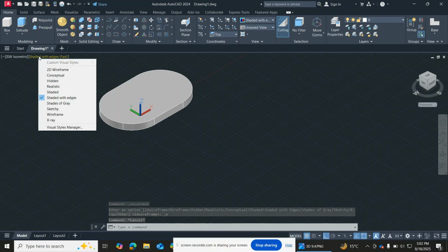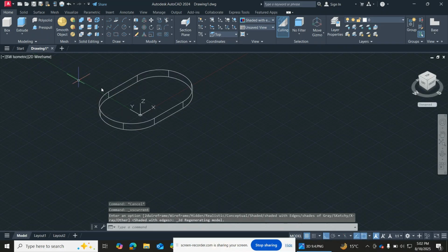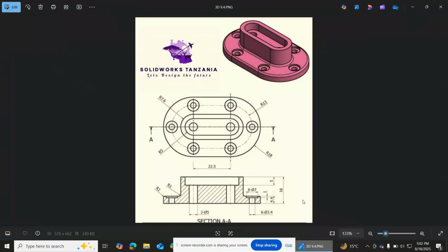Yeah, so let's go back to 2D wireframe to put other features. 2D wireframe, so what features? So I have to draw this guide slot, right? The guide slot has a radius of 13, circles with radius of 13, and then the center lines. Let me do that. And these bigger holes that go in by one thickness, they have a diameter of 7, radius is 3.5.